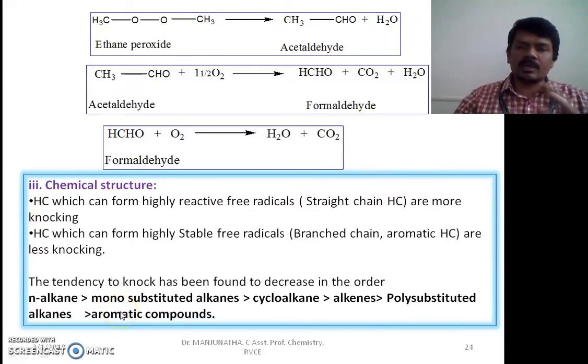Aromatic compounds, again because of delocalization and resonance, form more stable free radicals, therefore less knocking. Okay, it does not mean that if you fill petrol with more aromatic compounds, it will definitely not produce any sound or will have less knocking. However, we should also see the calorific value of the fuel, not only knocking. If you fill only benzene or toluene, the calorific value will come down considerably. So we should see all the characteristics, including knocking, calorific value and all the other important characteristics of the fuel. Here we are talking about only the knocking part.